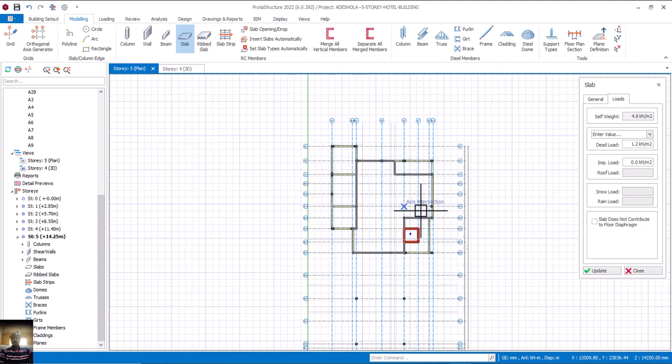So contact pressure now on this slab. To convert it, we say 50 kilonewton divided by the meter square, which is 2.6019. If you divide it, we should be having a 19 point something. Do your calculation over there: 50 divided by 2.6019, we are having 19.2. So that is fine.